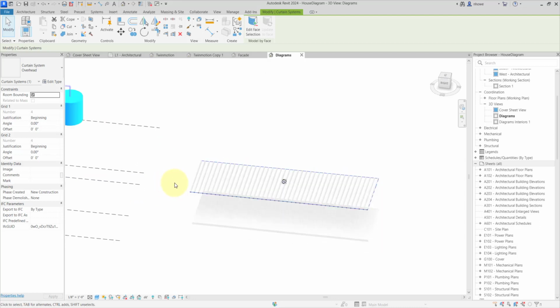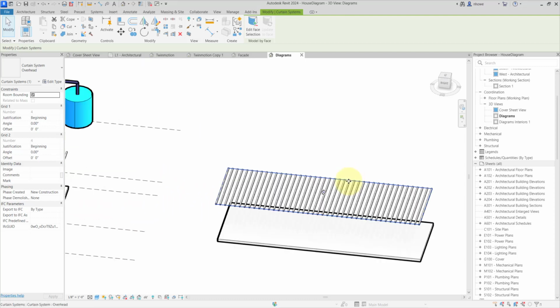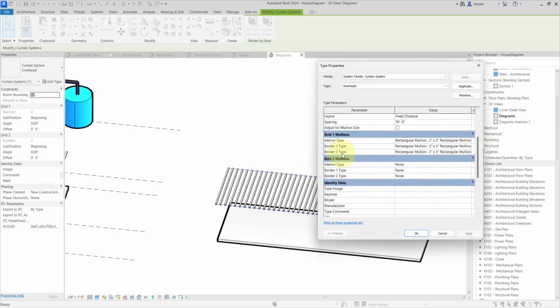But then you're going to start to assign actual walls to the mass. So then I can take this and assign walls to it, and I can assign floors, and ceiling planes, and so on and so forth. But then within this grid, I can start to assign the opposing structure.